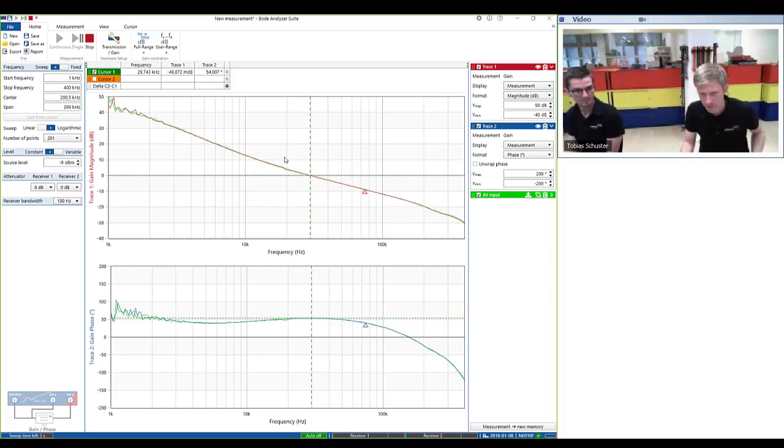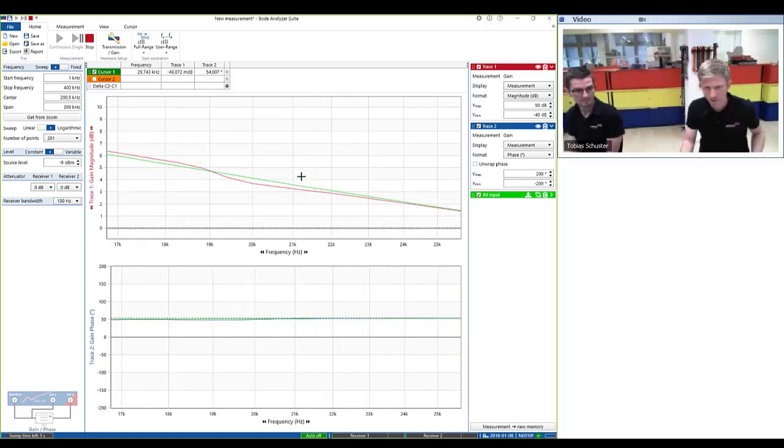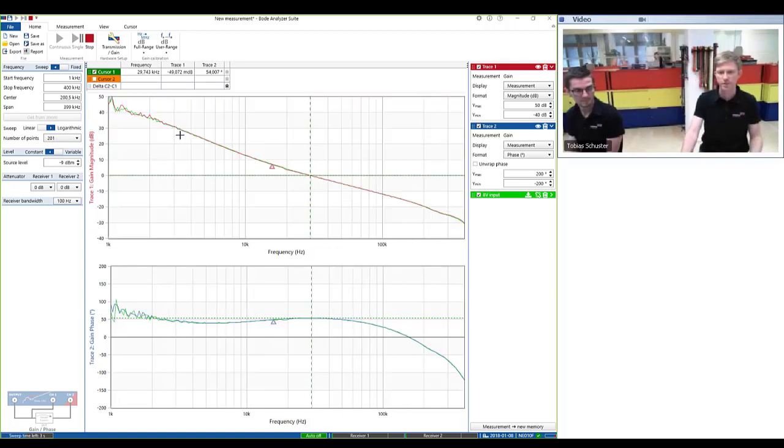There is a slight change here that you can see in this area. That's from the input filter, which we already know. But now we're going to reduce the input voltage slowly to check when there is going to really be a problem appearing. Okay, so we'll now slowly reduce the input voltage. Now we're at 7 volts. 6 volts. A little bigger.